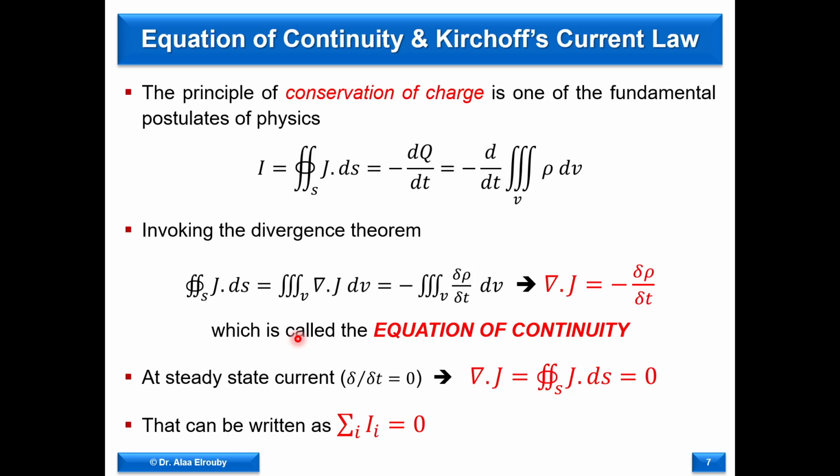So now let us see something very similar, or it is Kirchhoff's current law from the electromagnetic field perspective. In physics, we have the conservation of charge: the total amount of charge is preserved. So if we have a certain closed surface, the total charge out of this closed surface, as a function of time, is the current.